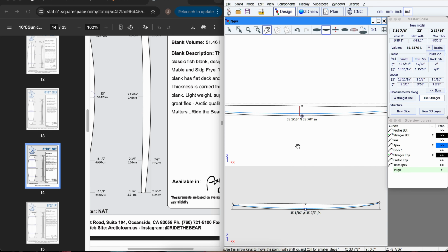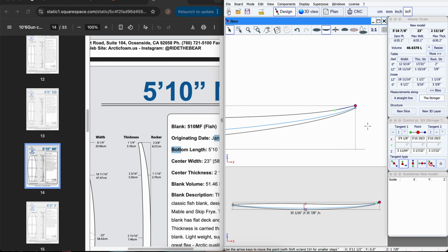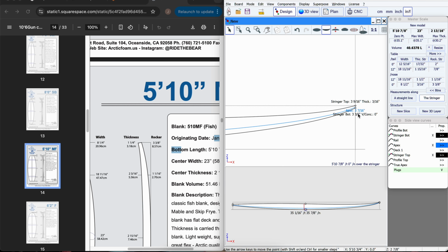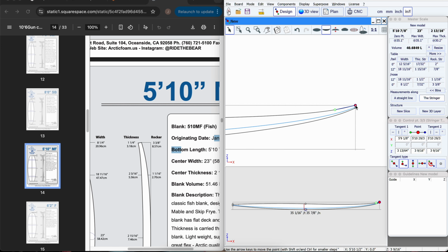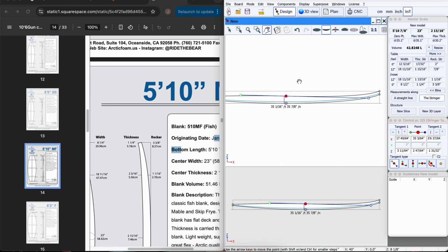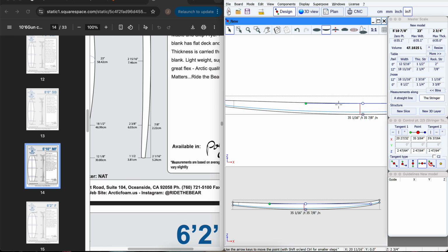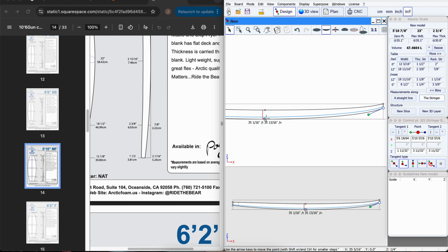Okay, so our rocker measurements are set. Now I'm gonna play with the tops, the points on the top, and by setting the foil is gonna set our thickness of the blank. So again, the thickness on the 0 from the nose is 1.25. So this is what we're gonna go and do. Don't be afraid, that's gonna be looking a bit weird, because especially the way the designing the stringer, that looks weird. But hang on, when we're gonna jump to the actual board design, it's gonna be way easier.